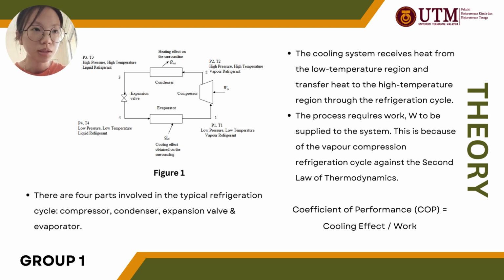This is because the vapor compression refrigeration cycle goes against the second law of thermodynamics, which is that heat can never pass to a warmer body from a colder body without any other change. In this experiment, the formula we apply is coefficient of performance, COP, equals cooling effect divided by work.